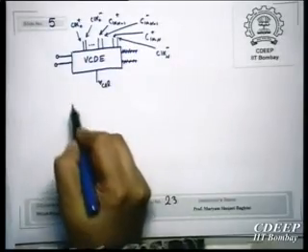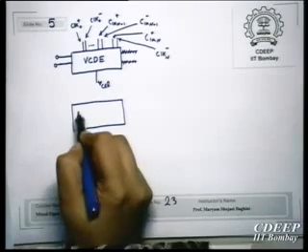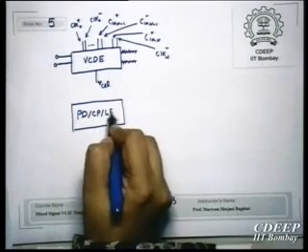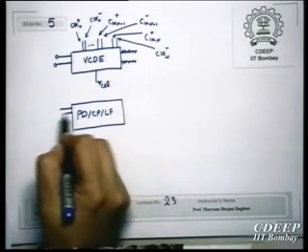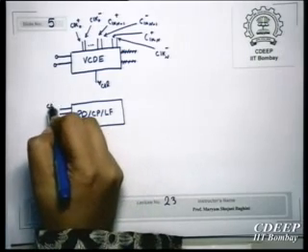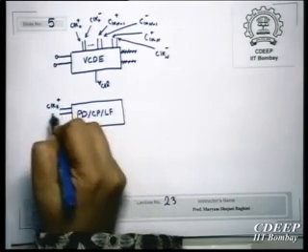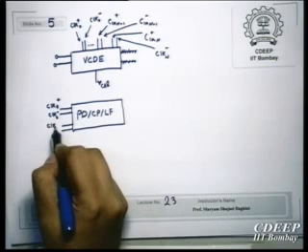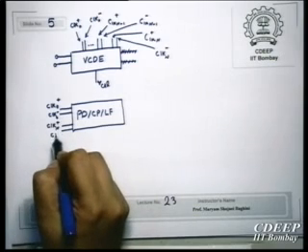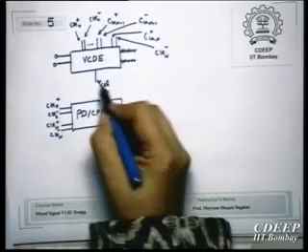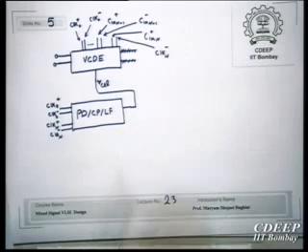Now they have again this phase detector and charge pump and filter. So what they give, everything is differential. They give clock 0 plus, clock 0 minus, clock n plus, clock n minus, and this will generate VCTL.